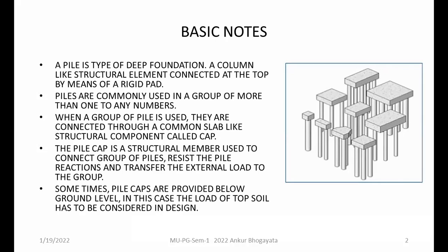So we are focused not on the pile design, please understand. We are interested in designing the pile cap itself, that is the pad component, because that is the primary component which holds all the piles intact and in place. Now there may be a question: what if we don't provide this component? It will not suffice the primary function of distribution of the forces. So pile cap is an unavoidable component of the deep foundation and a must-have component in the pile foundation itself.